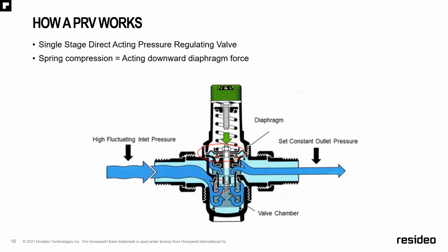And the way it works, it's very basic. Water comes in, it goes in through a pre-screen filter to protect the cartridge. And then you have a corresponding spring at the top. So when you dial it in to whatever output pressure you want, there is a corresponding spring at the bottom that holds the cartridge at a certain pressure that squeezes the water as it goes through to slow it down and also maintain its pressure. So if you do have a sudden increase of pressure on your positive side or on your feed, that spring is going to hold that cartridge tight and it's not going to react to that increase or that swing of incoming pressure.